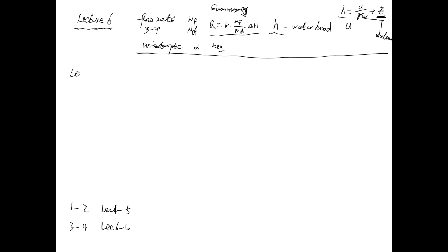Lecture 7. The main points: the Rankine lateral earth pressure calculation. You need to calculate sigma A prime and sigma P prime. For Rankine lateral earth pressure, you have the formulas to work out the active earth pressure and also the passive earth pressure.